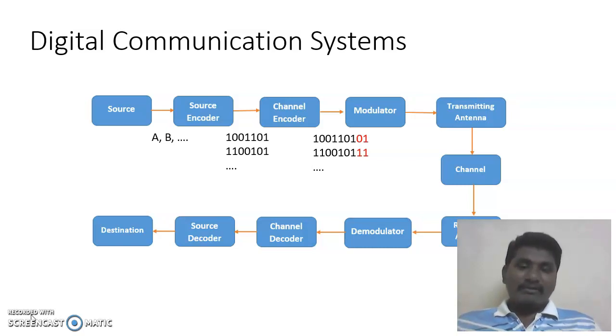Coming to the modulator, so far what we got is a binary sequence, and usually the same voice information in different applications needs to be dumped onto different frequency spectra. That can only be done by using a sinusoidal carrier to incorporate frequency translation.